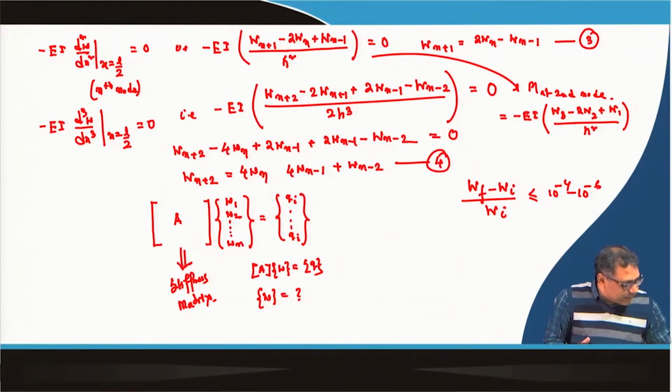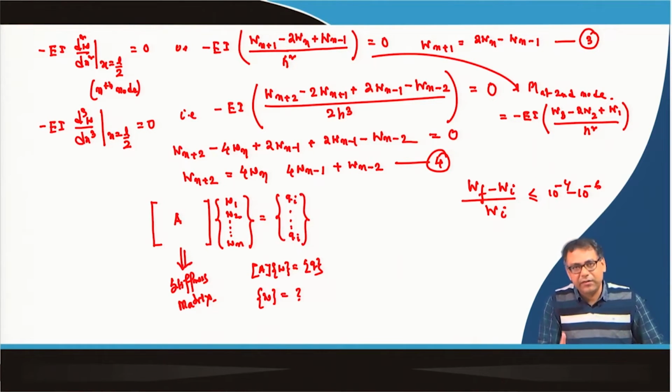So, this is the way you can solve the beam problem in the finite difference scheme, but this is for a beam with finite length. Similarly, you can use it for infinite or semi-infinite length by using the boundary conditions, because only the boundary conditions will change, while the equation remains the same.